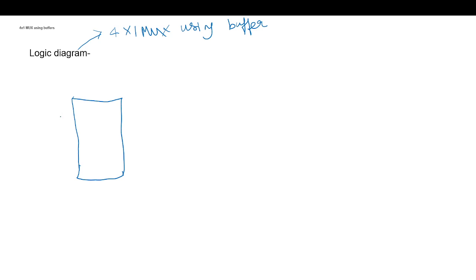First we'll start like this. I have two inputs, S0 and S1. These are the select lines. And I have some circuit which will give me four outputs to select, like if it is 0, 0, this line should be selected, so that I can proceed for the further circuit. So S0, S1 and this circuit. What is the circuit that will give me this output?